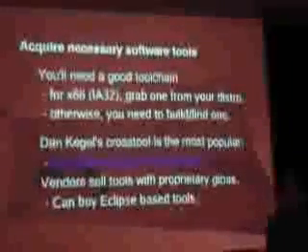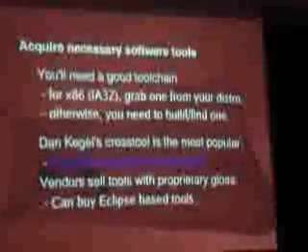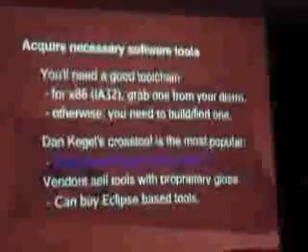A tool chain is a group of tools that you can use to do these things. That includes GCC, but not just GCC. It also includes the other tools you need in order to take an application and build it for a particular kind of computer. So you can grab one from your distribution if all you're doing is building another kind of PC-like system. But if you're doing something a bit more interesting, you might need to build or find one. The standard one we use in the embedded space is Dan Kegel's Crosstool.